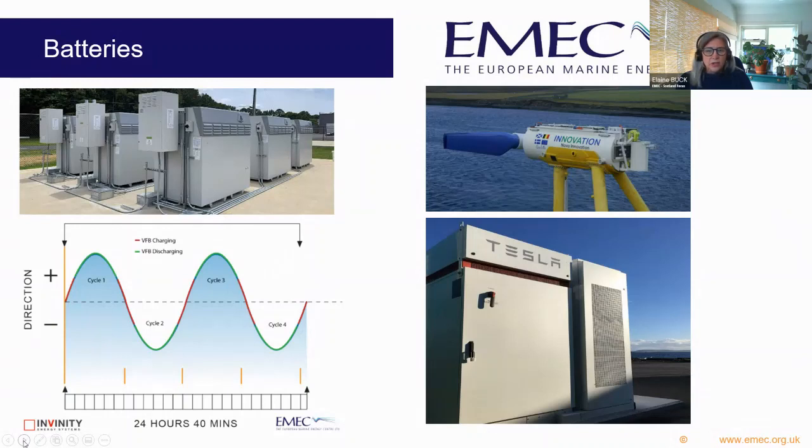The benefit of integrating these batteries is that they store the electrical charge in liquid form rather than solid, and they can provide these industrial quantities of power for a sustained period of time, and they can deeply discharge without damaging the battery itself. They can also stand fully charged for extended periods without losing charge. So these are all necessary qualities to integrate battery technology with renewable power generation and hydrogen production processes.